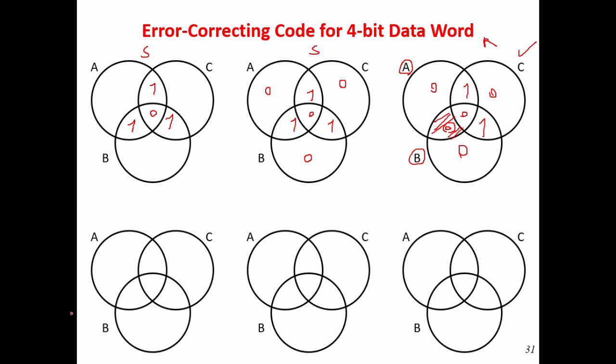For us, I'm trying to visualize things, but for the computer, it would be detected very easily. Suppose we want another example. Here, this is the information that the sender wants to send. First we need to decide about the parity. The parity here is odd, so it would be 1, here 1, here 1. And this is the receiver, right? And suppose the receiver received this.